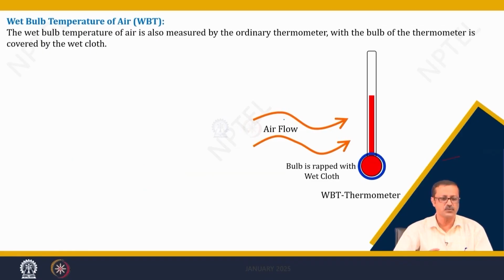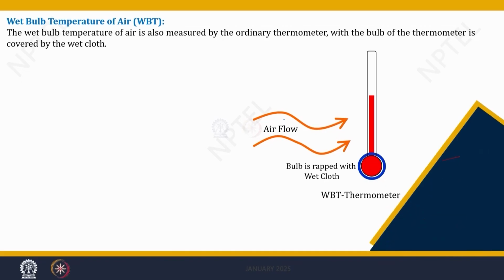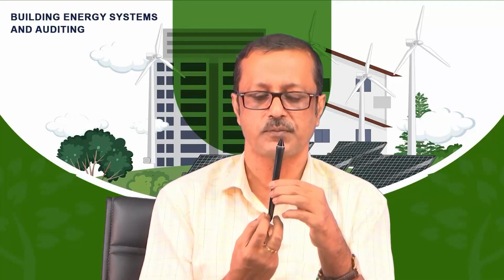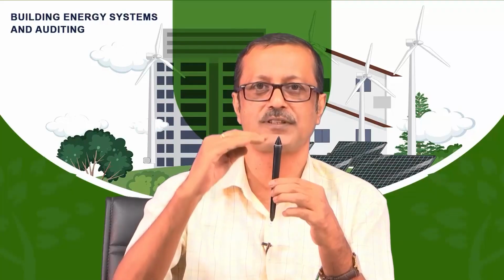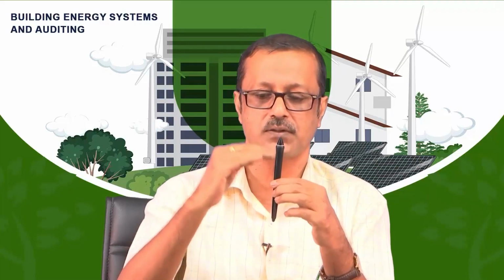Similarly, if I want to find out the wet bulb temperature, I put that bulb in a wet clothing or something. If there is an air flow through it, the air will take some moisture from the wet clothing in and around that bulb. So evaporative cooling will be there, and gradually there will be a drop of temperature with respect to the DBT.